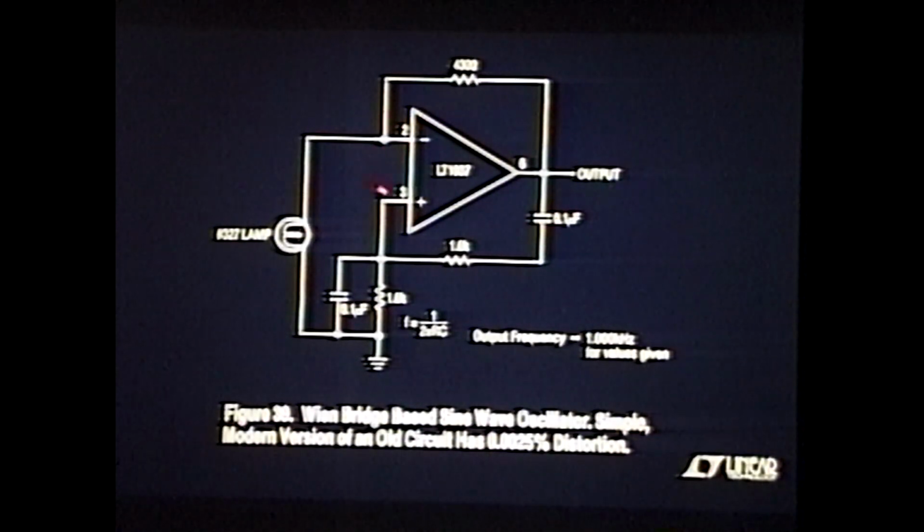You notice something about this circuit. This is moving at AC, oscillating. This point's moving at AC. After all, that's how the light bulb works. If this point's moving at AC, then this point must also be moving at AC. If you look at the dividing of these impedances here, you realize there's a substantial amount of signal at the inputs here when this circuit's running. There's a lot of common mode to this circuit. The amplifier is differencing this signal at frequency.